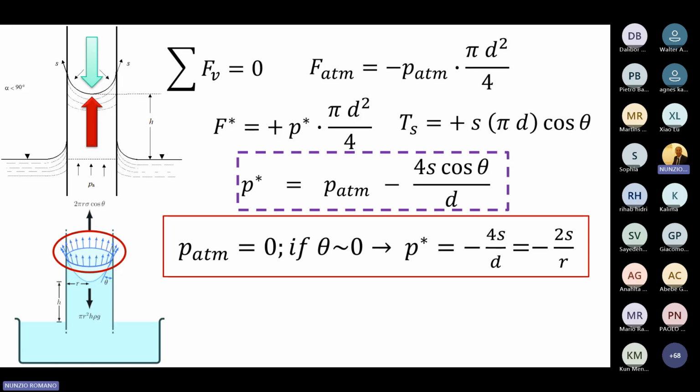I don't know if I understood this question well, but the fact that we have a pressure below the atmospheric pressure means that the capillary tube serves as a suction. So this is why the water rises into the tube, because of the cohesion also, and this is why there is the curvature of the meniscus.